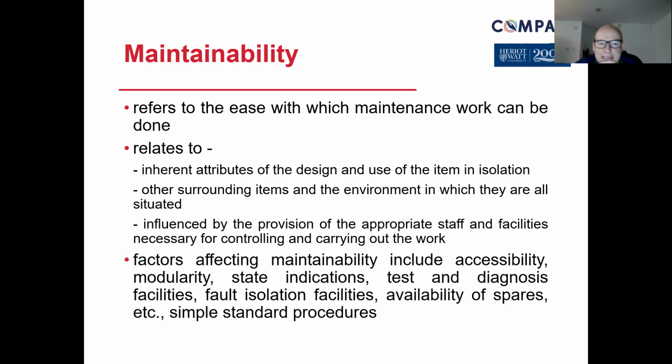Inaccessibility as well as accessibility, how modular it is, different parts that can bring up the overall finished product. State indications, you know, where are we at? What does it tell us? What alarm systems, what signals are there that say it's isolated, the power is on, the power is off? If in one of the states, what can happen? Could it result in a safe position or failure to safety, or could it leave it in an energized, unsafe situation? So indication is important to be able to identify what to do in various parts of the maintainability aspect.